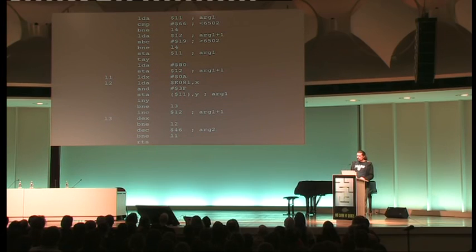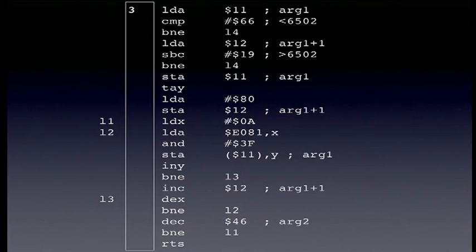If we go through this real quick, load from 0 page takes 3 cycles, because you have the load, you have the operand, and then you have the load from 0 page. The compare has 2, because the instruction is 2 cycles, it doesn't do any other fetch. This one has 2, because it's also a 2-byte instruction. If the branch is taken, there's an extra cycle there. We've had this one. This transfer is only a single byte, but we have a minimum of 2 cycles.